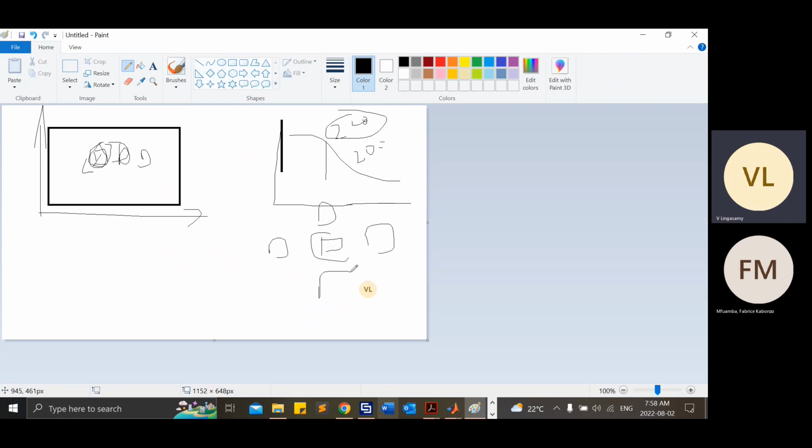That is how we are analyzing now. For example, Floquet port analysis assumes an infinite array approach. Infinitely, this element is extending, and I'm estimating the reflection phase for this particular element. That is how it estimates in CST or any tool. Here, in this unit cell simulation, we are getting 220 degrees for that particular size, but in reality it will not be 220 degrees. It can be plus minus 10 or plus minus 15.